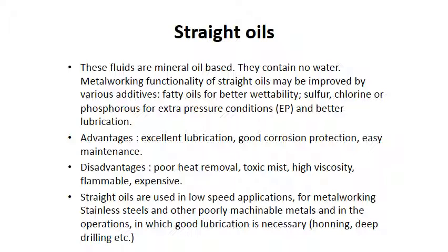Straight oils are usually used in low speed applications for metalworking of stainless steel and other poorly machinable metals, and in operations in which good lubrication is necessary, such as honing or deep drilling processes, etc.